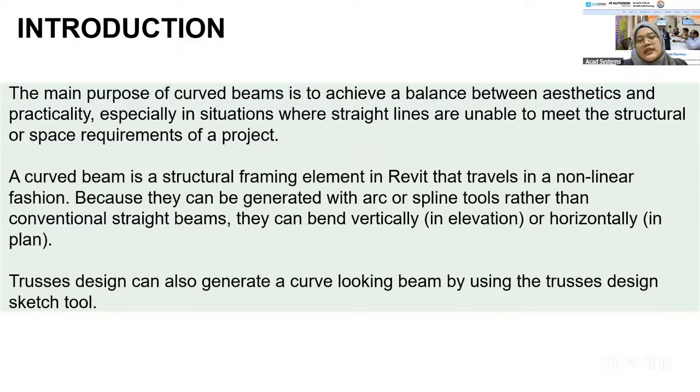Okay. So actually, a curve beam you can generate in Revit using the ordinary beam tools. This is because they are generated using the arc or spline tools rather than a conventional straight beam. So a curve beam can be generated using the arc or spline, and then they can bend vertically in elevation view or horizontally in plan view, right?